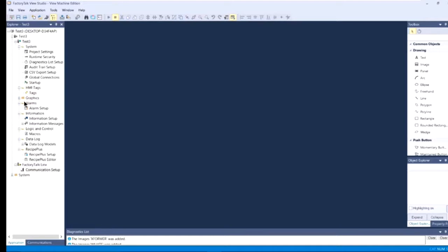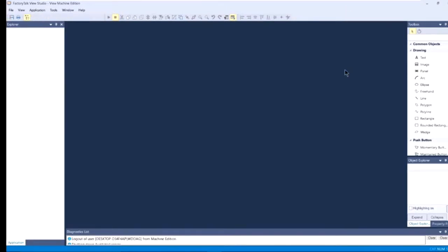The software for the 1400E has an import utility that can actually import previous versions before the 90s. The very first Panel View was DOS based, and the file from it can be imported into the 1400E software, saved, and then that file imported into this software. So through two steps, we can actually import the very first Panel Views that were available in the 80s. That demonstrates how the Panel View import works. That concludes my